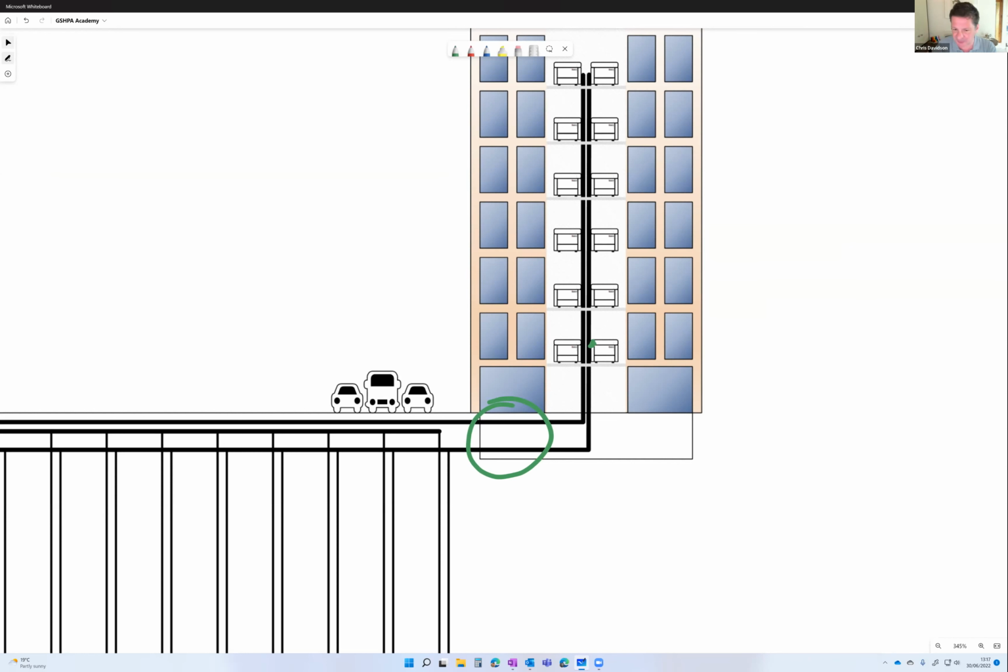So what does that give us? A couple of things. First of all, this heat network's now running at ambient temperatures, running between 0 and 25 degrees C. It would be down at 0 if this was just a pure ground source. It would touch 0 at the end of 20 years as the typical design parameters for ground source systems. If we've got any energy recovery going on, however, then it could be higher than that. And we tend to limit it to about 25 degrees because if you go above 25 degrees, heat pumps, when they're heating, tend to fall over on high pressure lockouts. Depends on the heat pump product involved, but it's a general principle again.